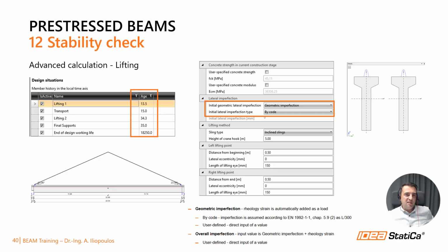For both, it is possible to set the length of lifting eye, which controls the vertical distance of the lifting point, meaning the center of rotation, from the top surface of the beam. The lifting point is the point at which the flexible support joins the rigid body. A line passing through the lifting point at each support forms a roll axis.